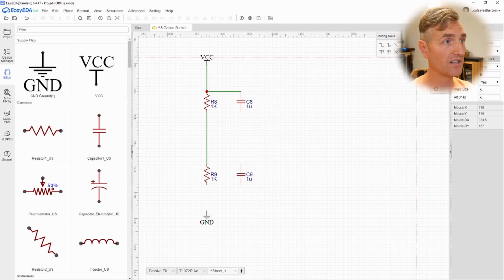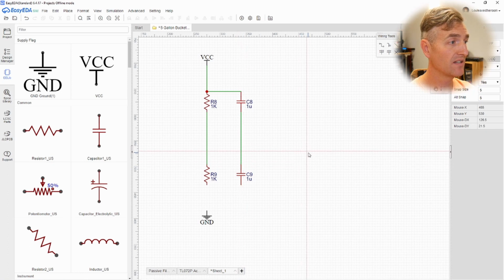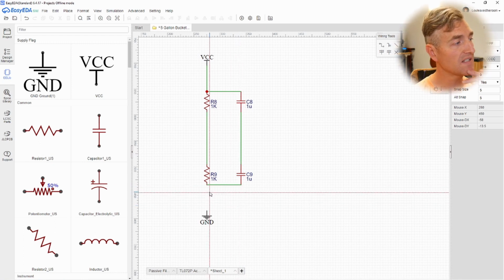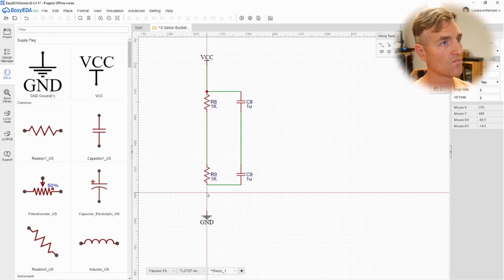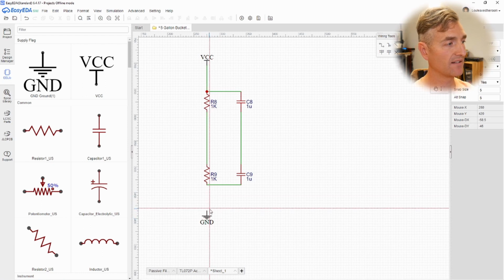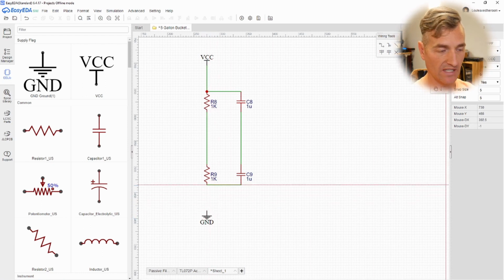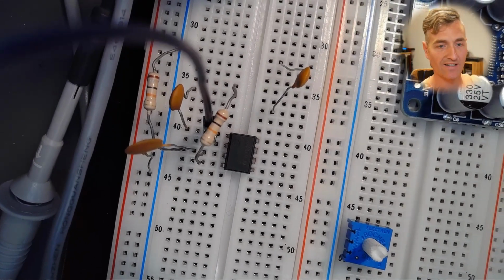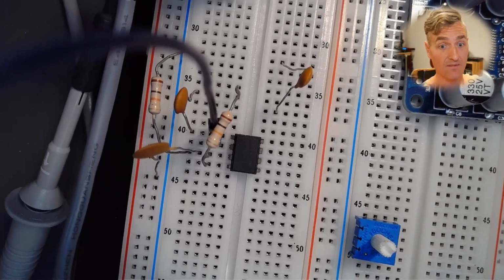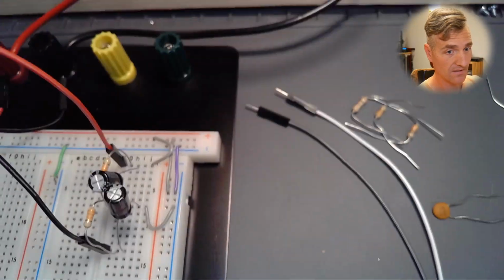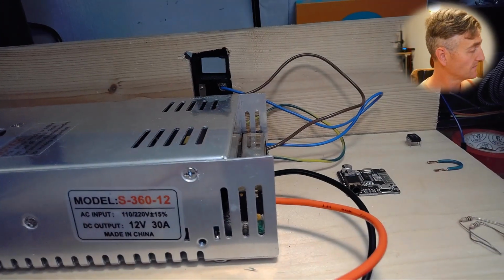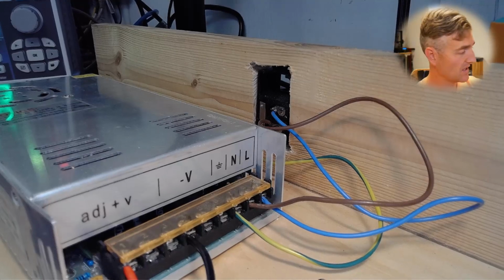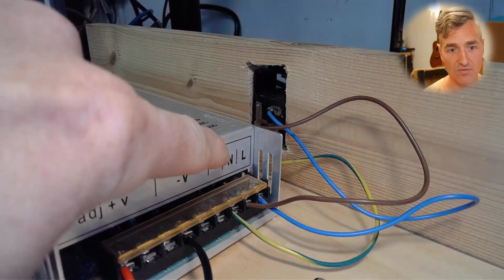So what we're ultimately trying to do is use our resistors and capacitors to take this single 12-volt supply and make a positive and negative supply out of it. So one of the things that I had to do with my supply is, if I turn on my webcam, let's turn on my webcam here. I think my webcam is super zoomed into my op amp, which we'll get back to. I turn on my webcam and look at my supply. I think I can even come around here. So you can see I have positive, negative, and I had ground.